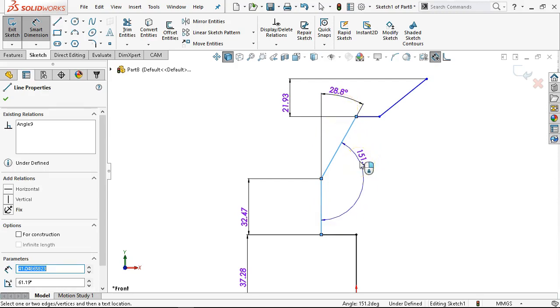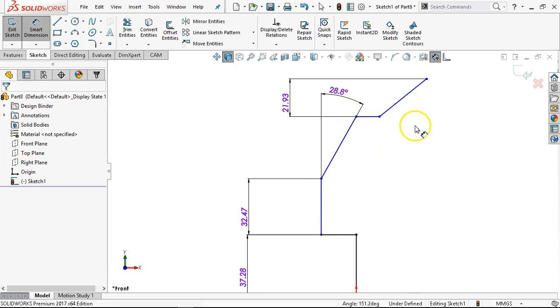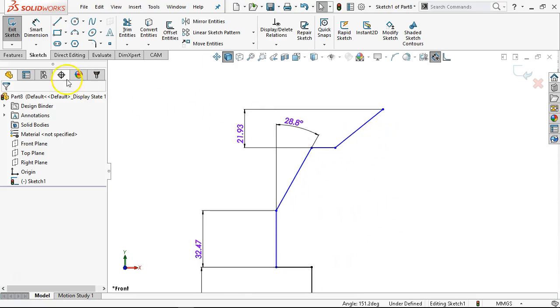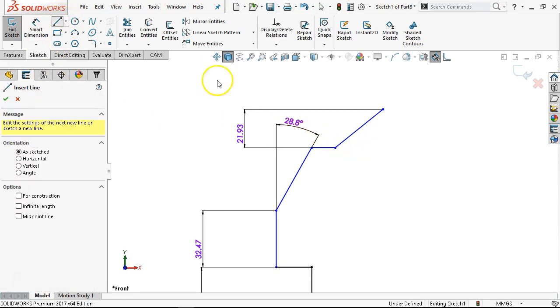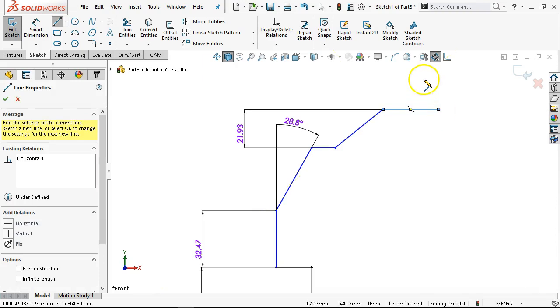All right, but in a case where this was kind of floating out in space, or starting from a location that was not convenient to pick up, and at some point you're going to see that four-headed arrow, you're going to generate it whether you intended to or not. Be aware of what it's doing, and most of the time you can just hit escape and go back to your other dimensioning to pick it out. All right, so we've got that one. I need a line for the 230.